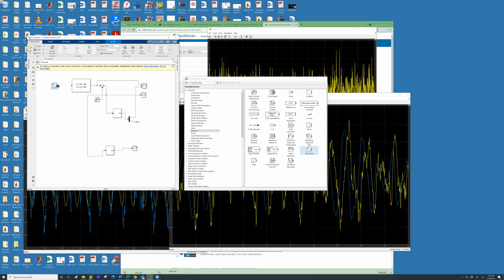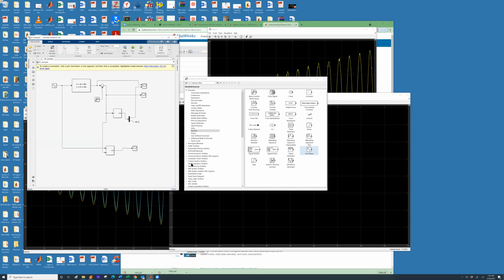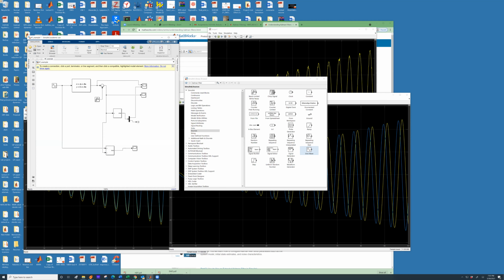So now you have not a zero input, but a sinusoidal input. Here you can go to options, add a port U, then feed this sinusoidal input to this port and run. And again, see.